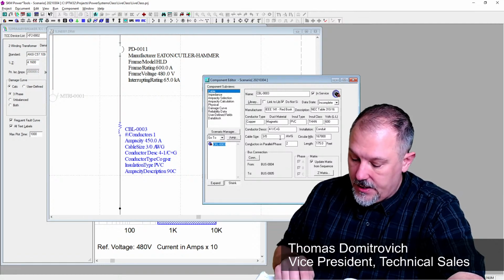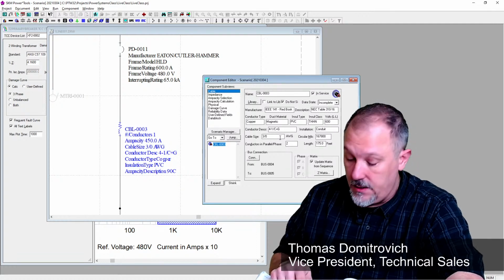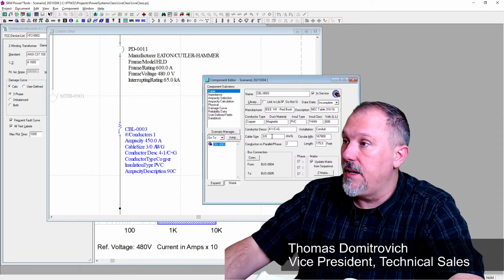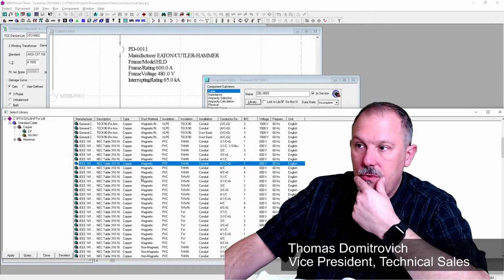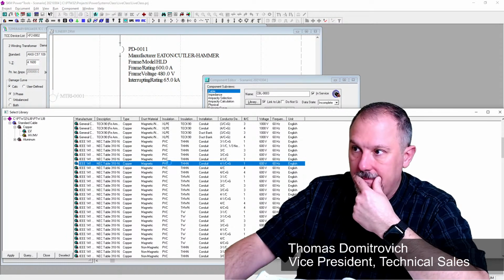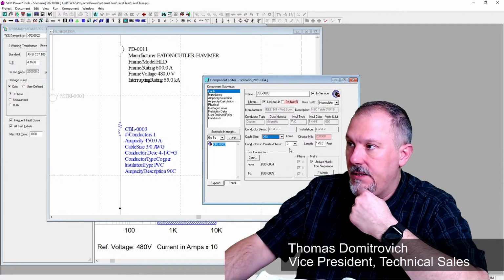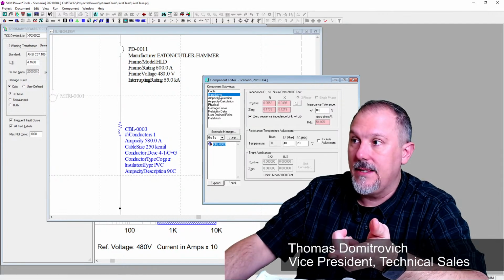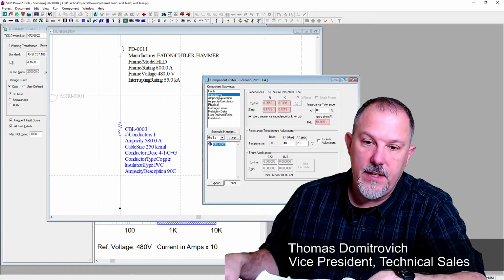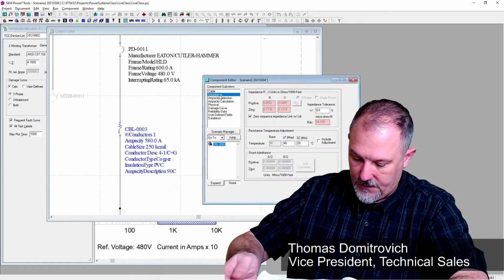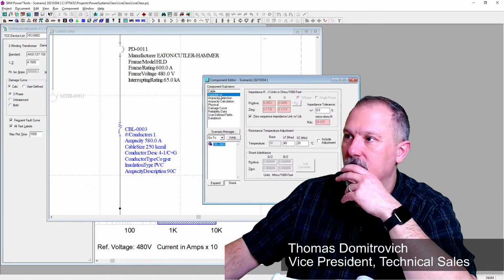To get 500 amps, I could put two 250s. So two 250s will get it for me. And so here's what I'm going to have to do: two 250s. If I do two 250s, the same footage, I've got to go back to the impedance, and here's what we did. 110/14C2, parallel 250s. There we go. So we parallel two 250s. That's what we would do.